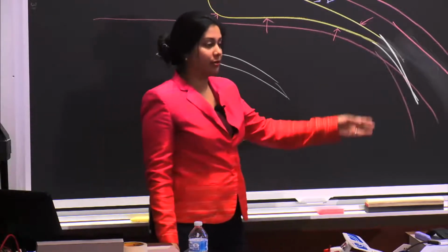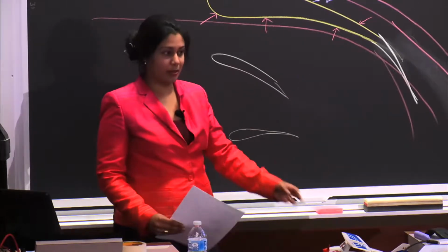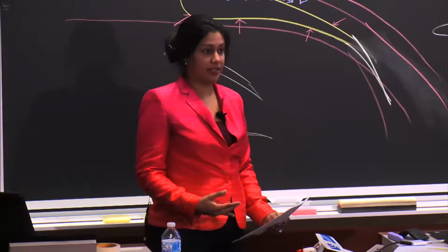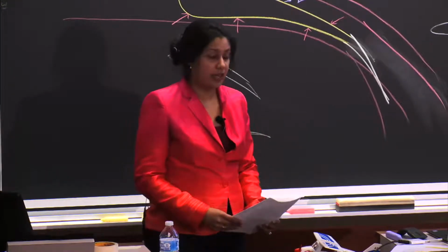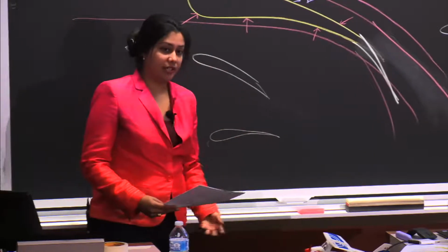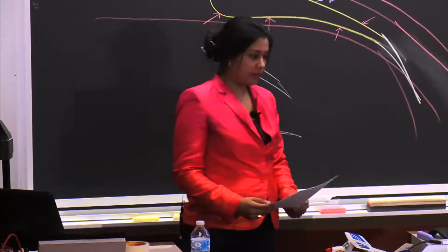Now we don't have smooth flow. We definitely have turbulent flow. We have spinning flow, and we have air molecules hitting other air molecules. It becomes extremely difficult for us to model all of those air molecules. We really can't do it. So going from two dimensions to three dimensions is really a limitation of a lot of the equations that we have to approximate lift.